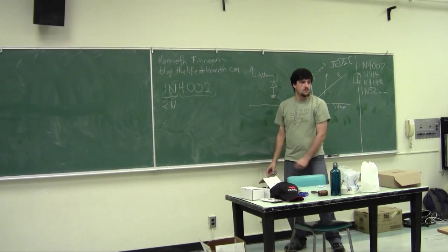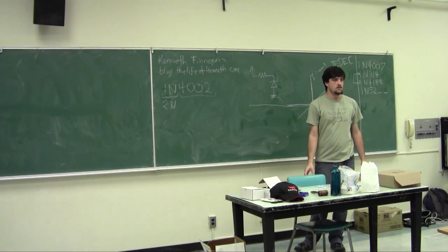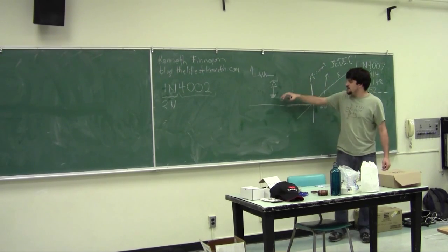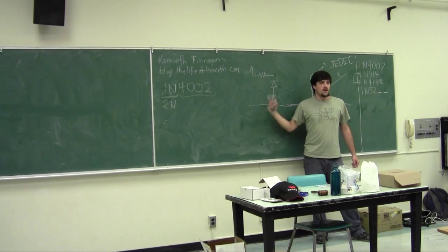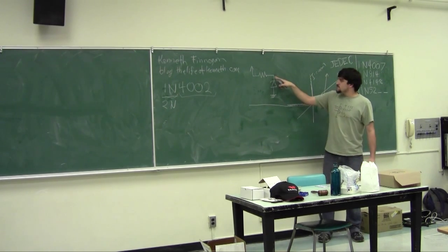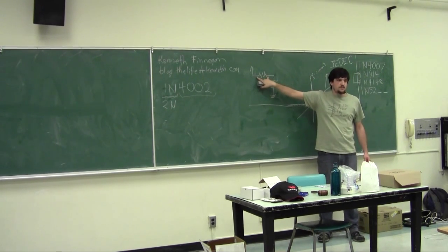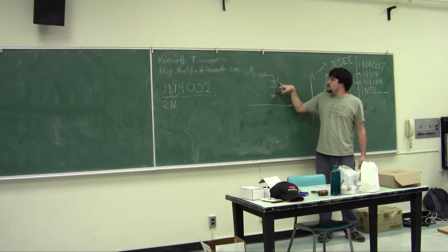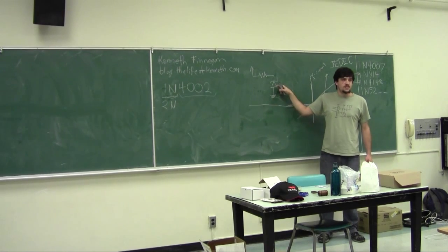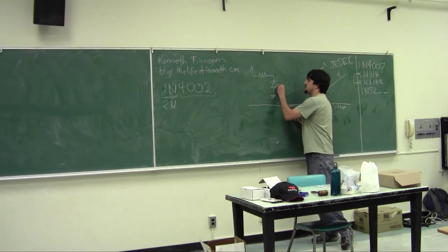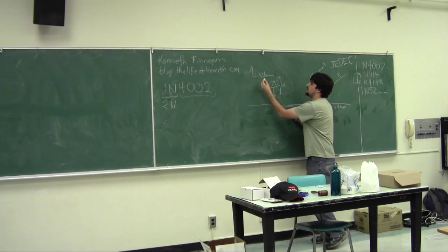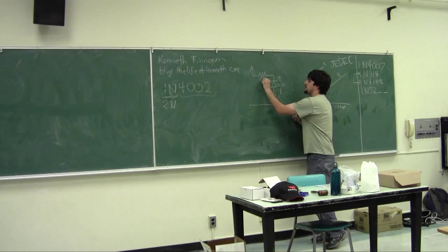Yes? So it doesn't drop more than 5.6 in that direction? If you were to apply more than 5.6, the current would exponentially grow. That's why we had this resistor here, so if we apply 10 volts here, current would start to flow through this diode at 5.6, and so we'd have 5.6 volts here, and then we'd have the 4.4 volts left just across the resistor.